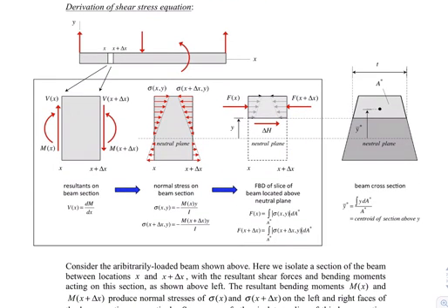We're looking here at a beam with some arbitrary loading on it. I take a section of that beam, a section of width delta x, that's this dimension here. As I cut this away, I'm going to have a bending moment on the left and a bending moment on the right, which will likely be different. They have a shear force left, shear force right. I'm going to focus in on what the bending moment M does. We know that the stress is going to be My over I. Above the neutral axis, with M shown as it is, it's going to be sigma in compression, and on the bottom it's sigma in tension.